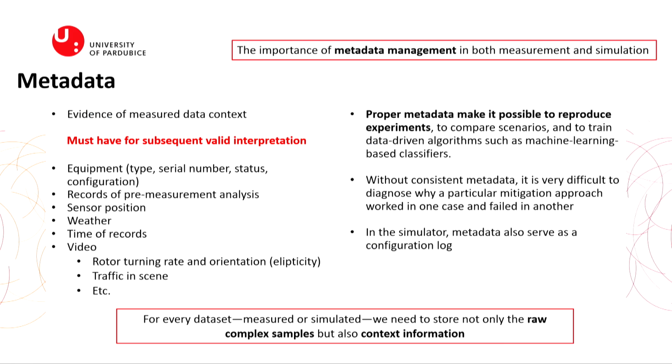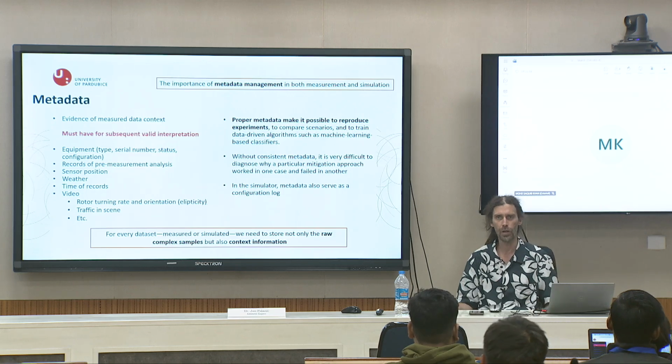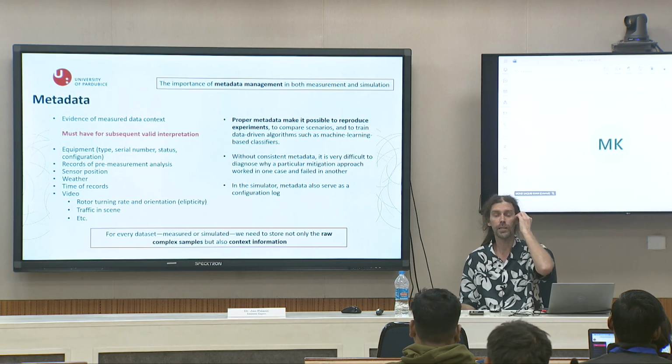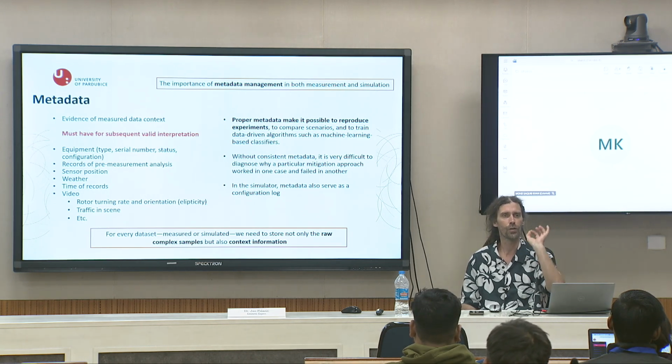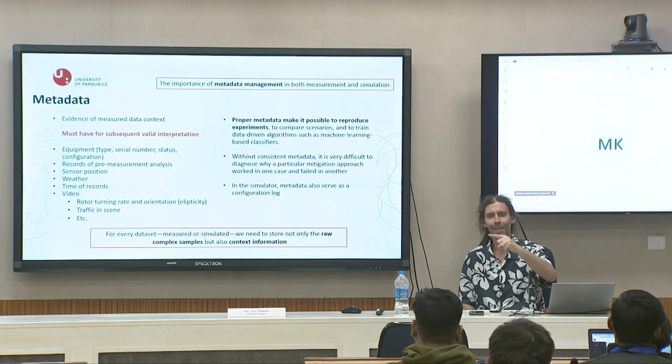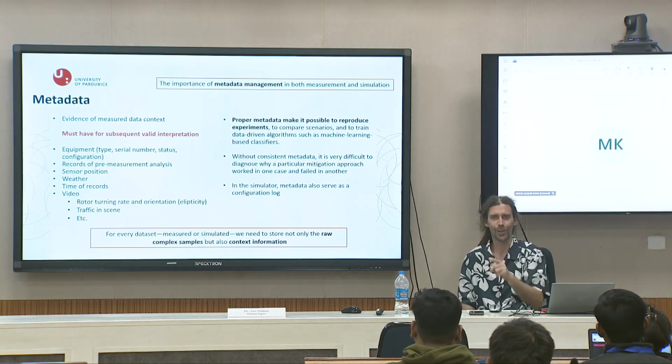And about measurement, there is one thing: you never know the speed of rotation. Do you agree? Because you just come to the site, start the measurement, and you don't know how quickly it rotates. Always make a video recording, because from the video you can easily detect one rotation.